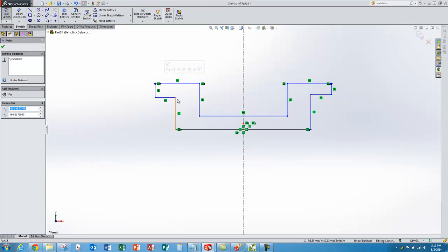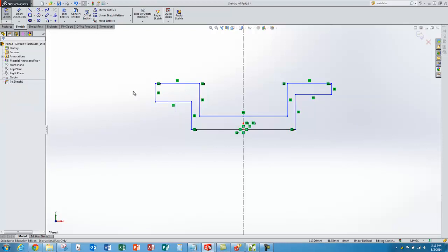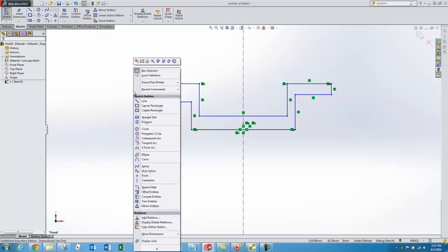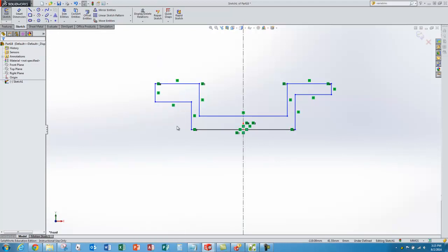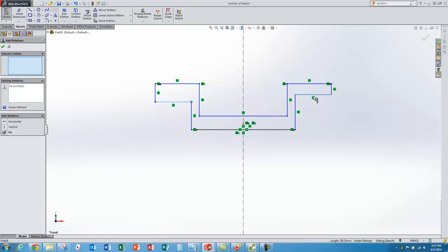Now as I move these corner vertices around, I'm starting to see that my sketch is getting geometrically constrained. I've still got one problem here. These lines ought to be collinear. So this is a good way to find missing constraints, by dragging those corners around. So if I right click, add relationship, I'll add one more geometric constraint between that line, and one of the options is collinear.